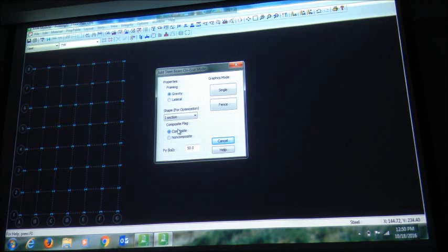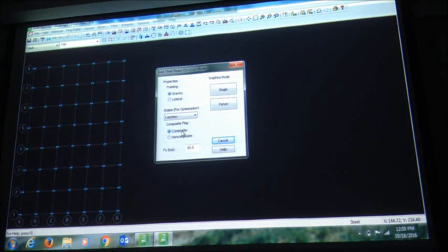We are trying to add some beams for the composite beams, since we have a floor deck and the floor deck usually has concrete on top of that. So when the beam bends, it bends with the slab. If it bends as a positive bending, the top portion of the beam is in compression, and that includes the concrete part on the deck also.